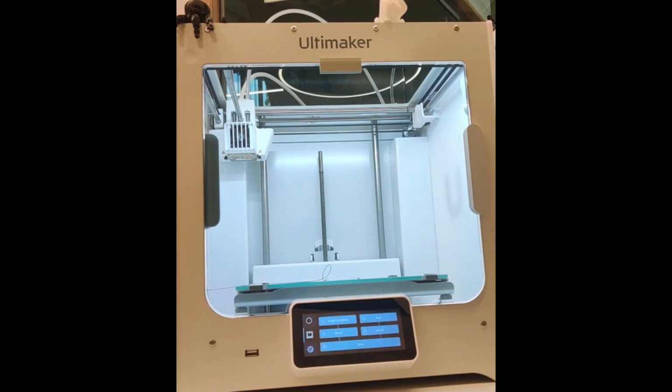And it'll actually already show you what's loaded into Bay 1 and Bay 2. So in Bay 1 we have Tough PLA Black, and then in Bay 2 we just have ordinary PLA. The reason it says it's Tough PLA Black is because in the first bay it's actually Ultimaker brand PLA. So we can change either one of these we want. This is also how you would go about changing the print cores. Follows just about the same instructions. So we'll walk through the step-by-step instructions together.